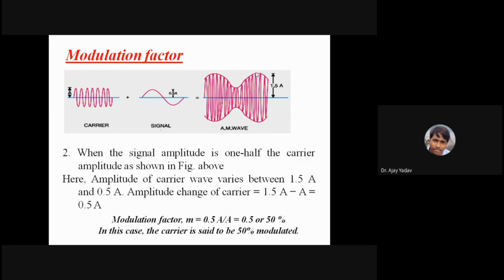So if they get interfered, they get absorbed here by some means, those amplitude variations and this data amplitude variation will get mixed up, and for the receiver it will be very difficult to distinguish between the actual data signal in the amplitude variation of your resultant AM signal and the noise signal.